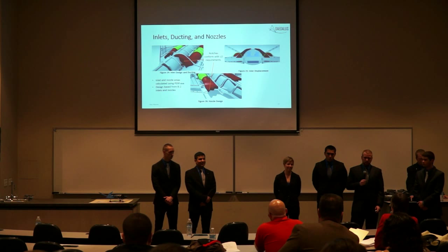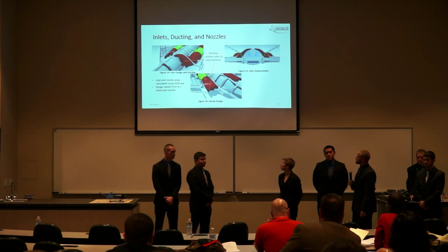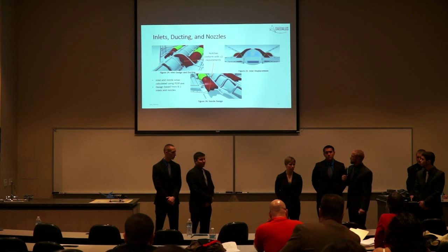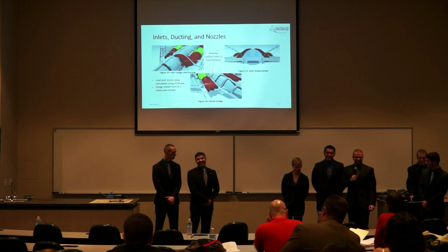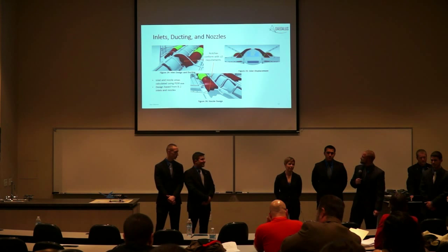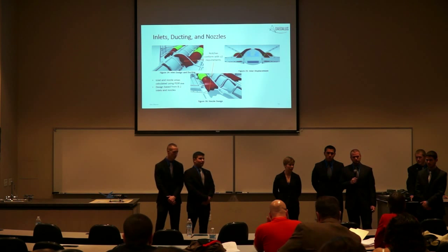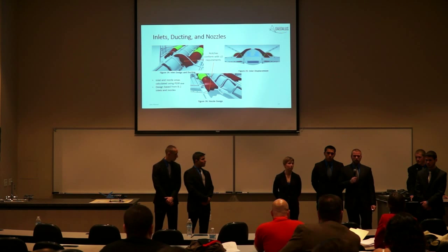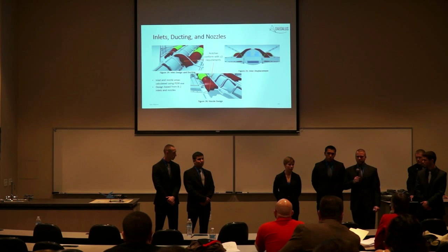So you've got a fairly long duct, and what do you expect to happen to the total pressure as it goes through that duct? It's probably going to increase since it's... Total pressure? Oh, in other words, you're going the wrong direction. It's going to decrease. It'll decrease a little bit, so just be aware that the total properties that perf gives you are maybe a little bit optimistic. When you start putting in a longer duct, you may need a little bit more area to pass the mass flow. Okay. We intend to further analyze the ducting, the inlets and nozzles in detail. Okay.